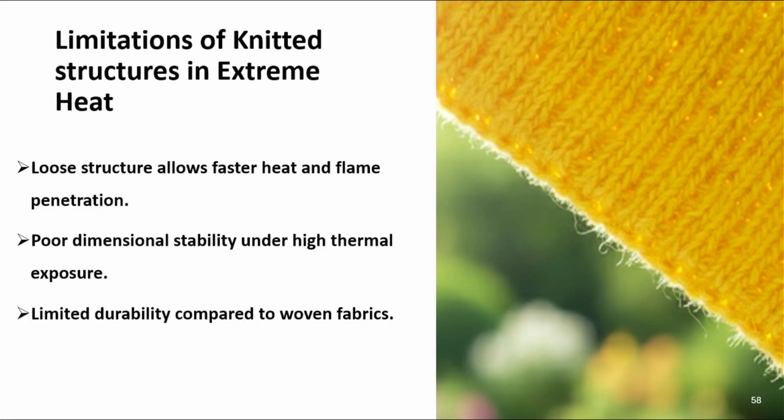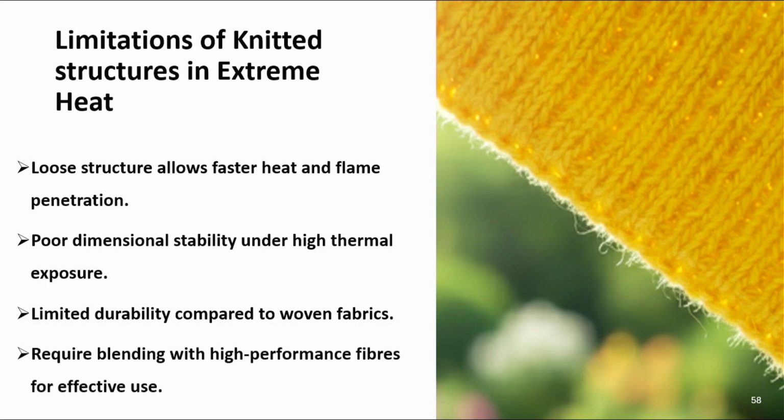There is limited durability compared to woven fabric, because woven fabrics are much more compact and structured. Here the durability is less because of the loop structure. Loops can get distorted easily, particularly in weft knitted structure, and it requires blending with high performance fiber for effective use.